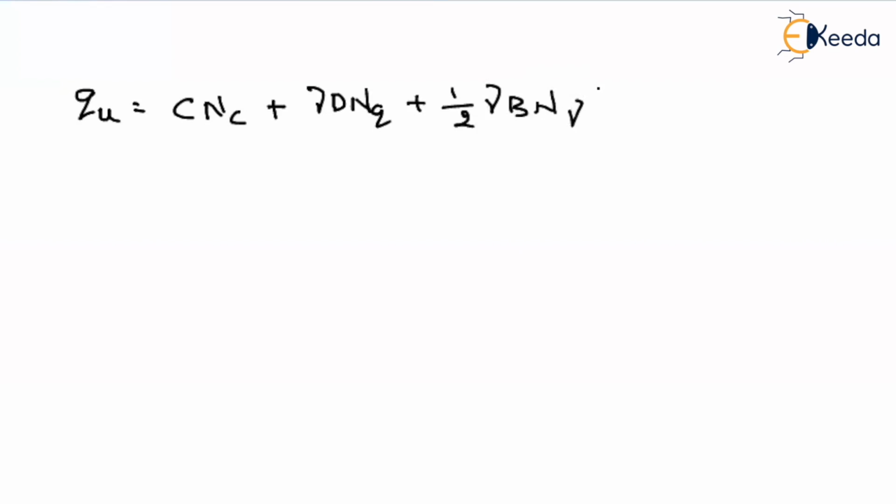For that, let us understand the bearing capacity terms given by Terzaghi. After that, we will see one by one. So, if you recall the bearing capacity equation by Terzaghi, what is written there? For the continuous footing failing by, let us say, general shear failure: C into Nc plus gamma D Nq plus half into gamma into B into N gamma, right?